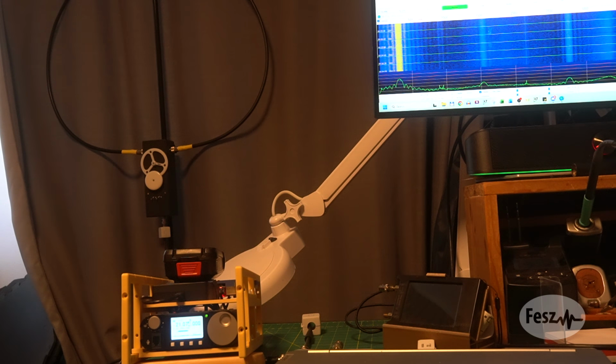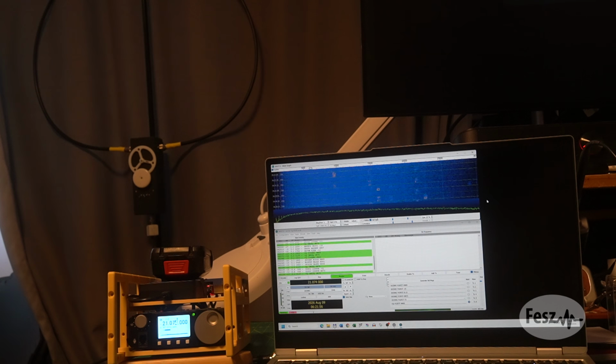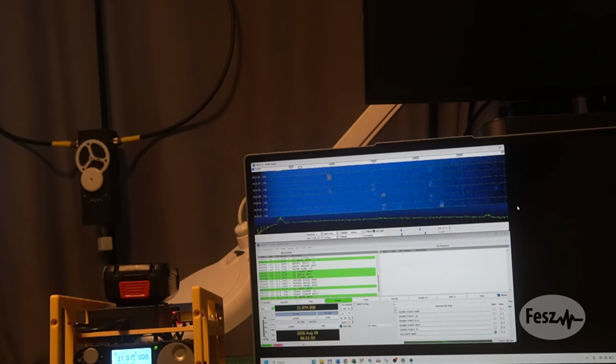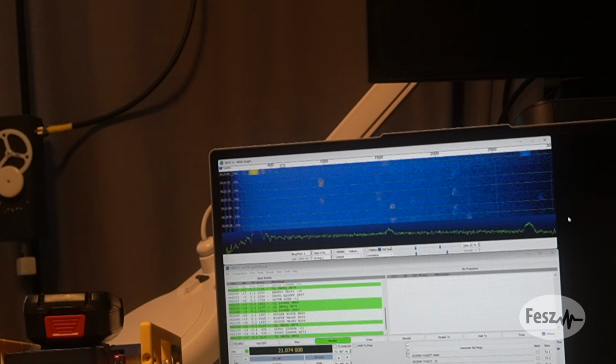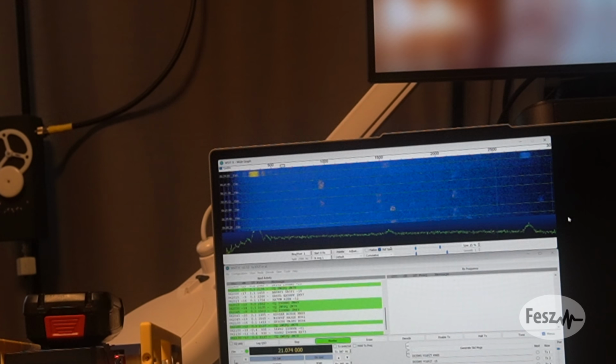What did help, however, was a simple but highly effective change. The noisy waterfall only occurred when the radio was being connected to my main PC, so a large full tower PC with dual monitors. When the same radio, same antenna was connected to the laptop, all the noise disappeared. When I left the setup on the laptop and turned on the PC, well, the noise reappeared. So yeah, this was not a lack of filtering issue, but rather noise from nearby electronics issue. You learn something every day.